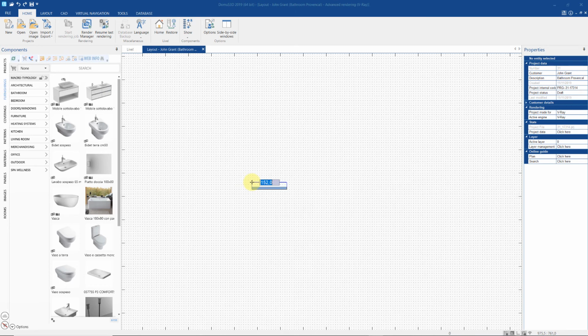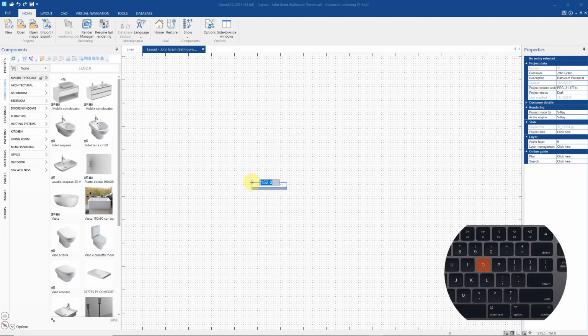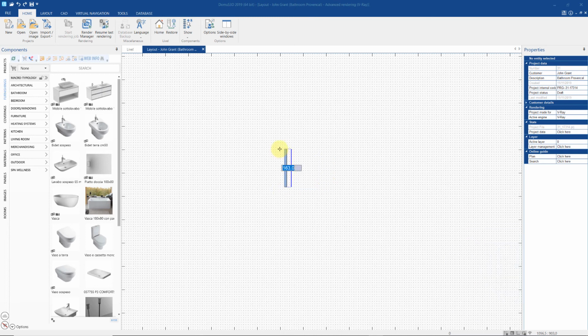If we want to design slanted walls, we can deactivate this default control by hitting the O key. We can activate it once more by again hitting O. You should always draw clockwise, as this will help us avoid problems with certain actions later on in the project. Once you indicate the direction that you want to move in with the mouse, you can type the exact length that you want the wall you are drawing to have.